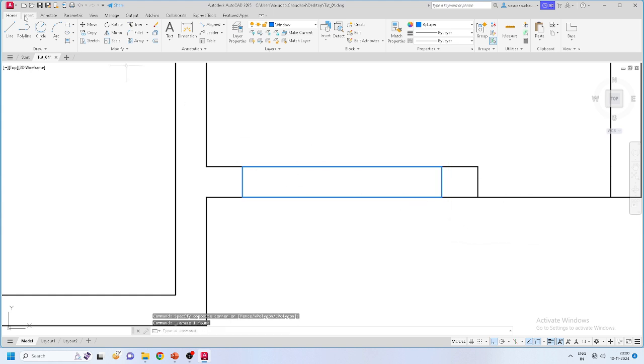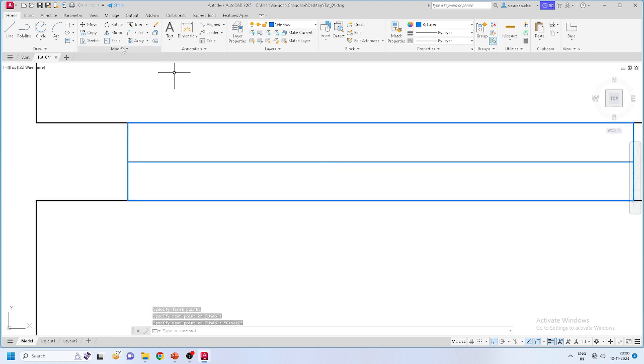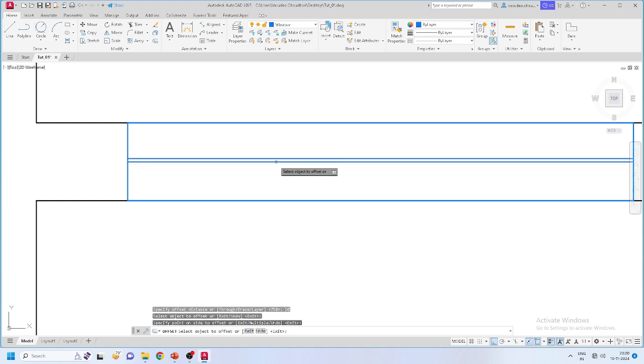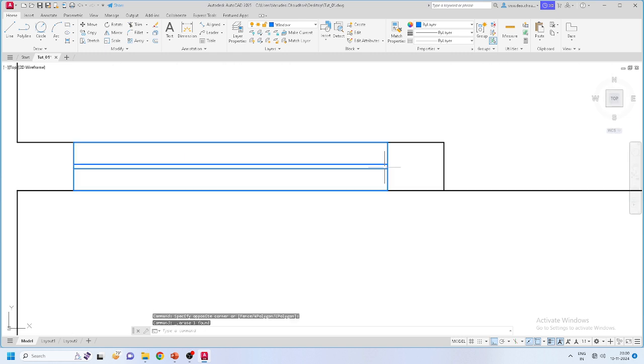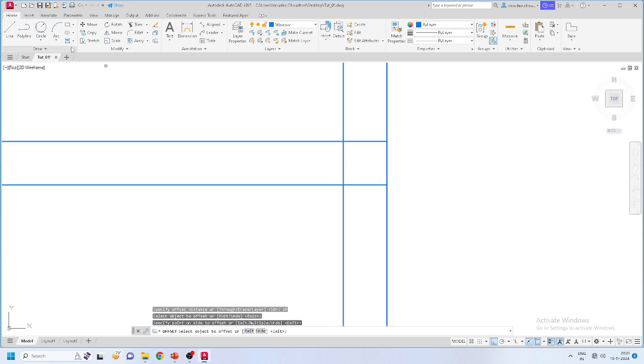And this is my window, but definitely you should have a window frame also. Depending upon the type of window you can decide this detail. And then I'm creating this with a 20 mm thick window frame, so I'm just putting this one here. So this is my window. Definitely for more detail, you can even have this offset, and then I have to have some wooden section here. So maybe I'm taking a 20 mm offset, right? And this part I should show using a hatch command.